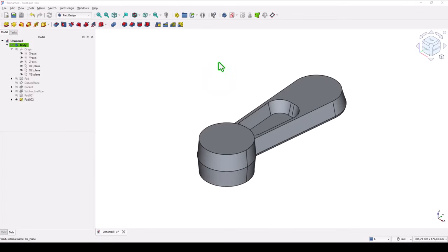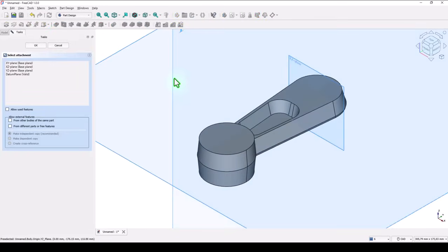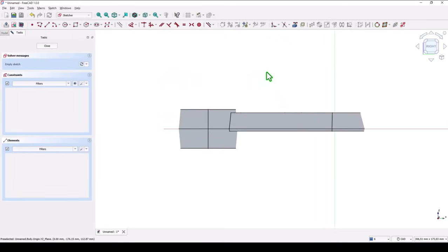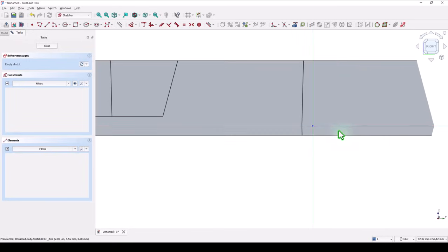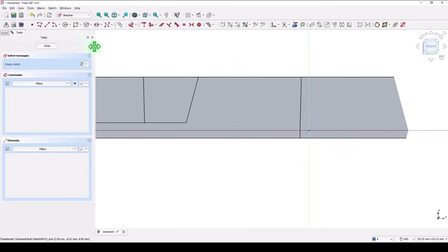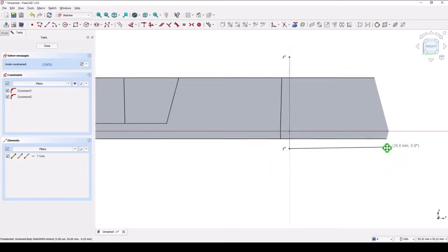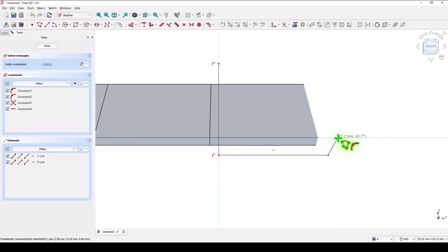We'll use the tool revolve, new sketch in this plane, F7 is in Inventor, and view section is here. Why? Because we have this point. We draw a polyline starting from here, going here, and then horizontal outside, sloped here, and horizontal.